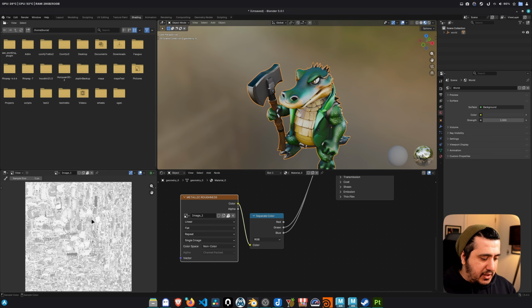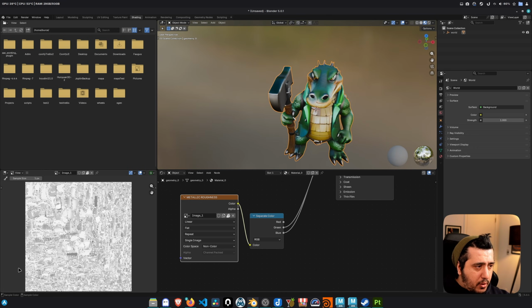And this is something I generally see also in some of the tutorials. There is no in-between value for a metallic map in PBR. Something is either metal, 1, or dielectric, 0. There is no 0.5 metallic. If you want a rougher metal, your metallic value is going to be 1, complete white, and you make it shiny or rougher with your roughness map. This is a very big misunderstanding that I see lots of times. So there is no metallic map like this.